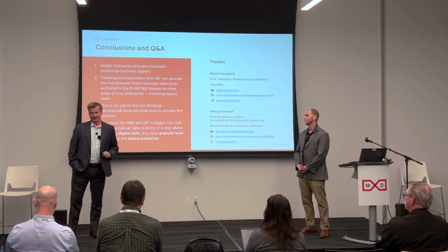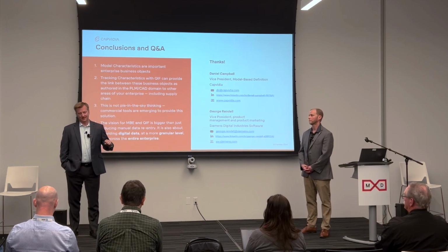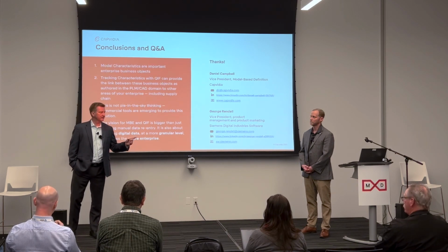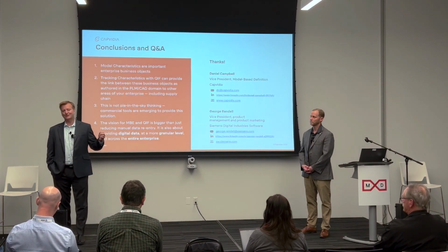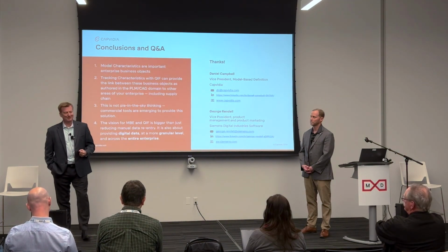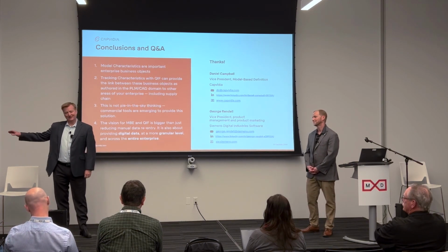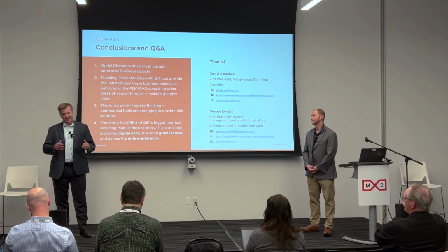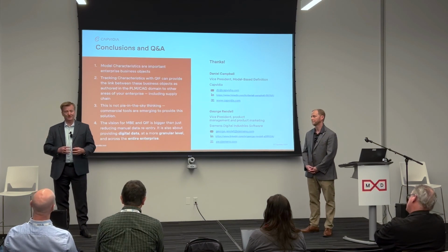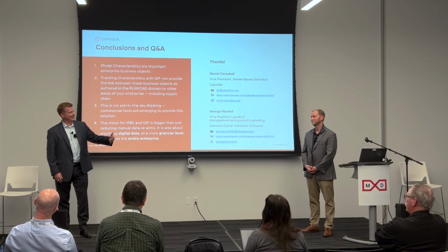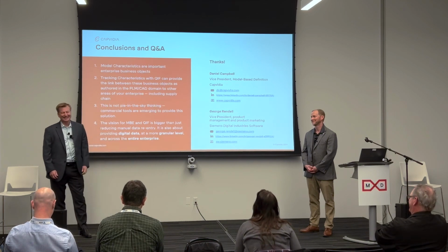IGES doesn't support characteristics. The other MCAD systems don't have characteristics, so direct translators to and from NX and Pro/E Creo, direct translators to and from NX and CATIA, NX and SolidWorks don't support characteristics. So there's a kind of a sales positioning answer, and then there's also the technical answer. Might STEP at some point in the future learn and then catch up in answer 1?